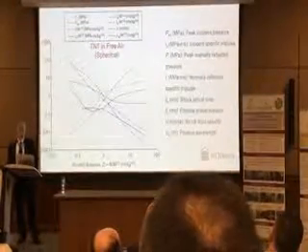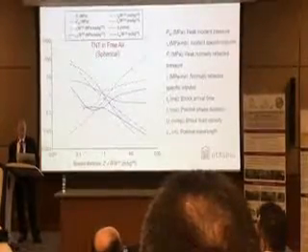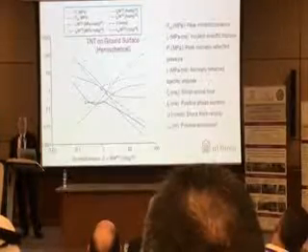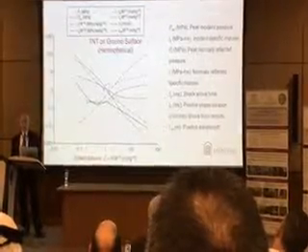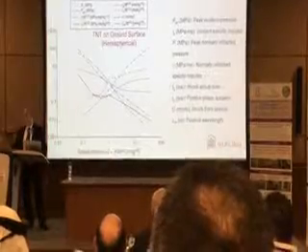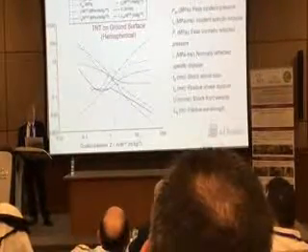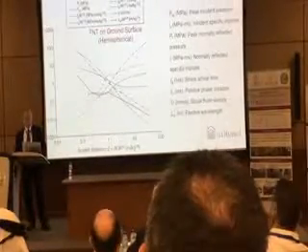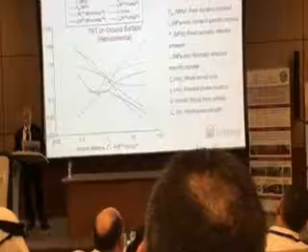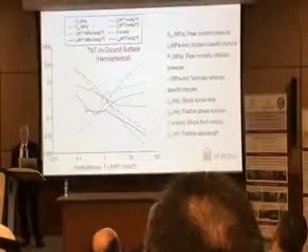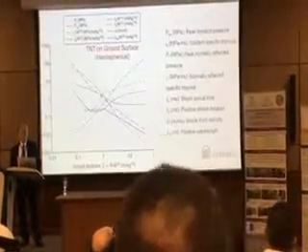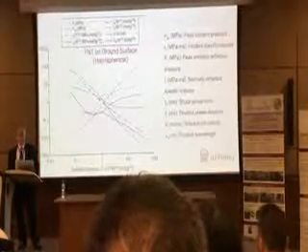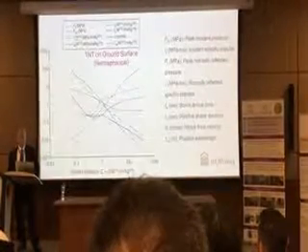So in this, they have different charts for TNT in free air and TNT in hemispherical ground surface, depending on your shape. They also have curves for inside explosions. But if you enter with Z, let's say Z is 1, and depending on which curve you interact with, dotted line gives you reflected pressure, dashed line gives you incident pressure, and then solid line gives you impulse.